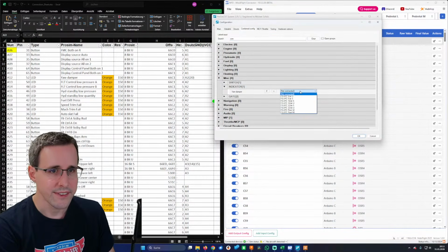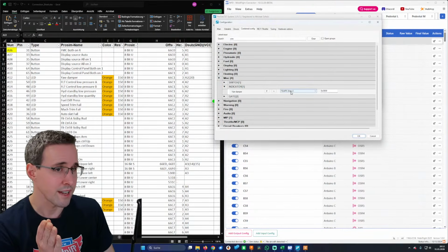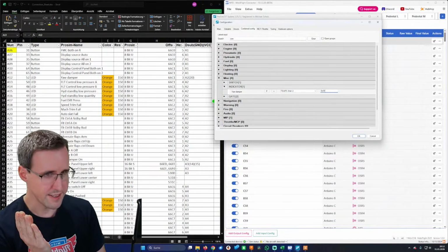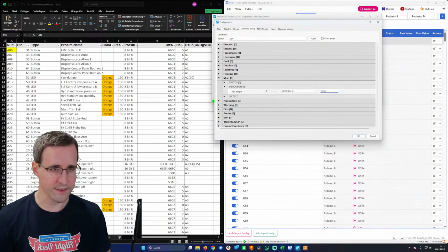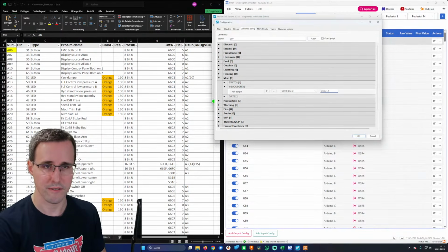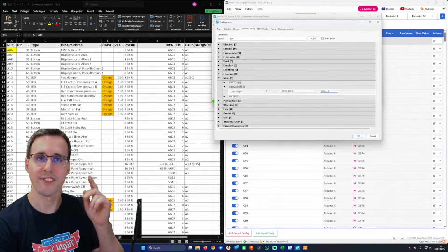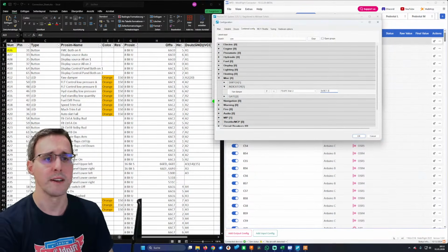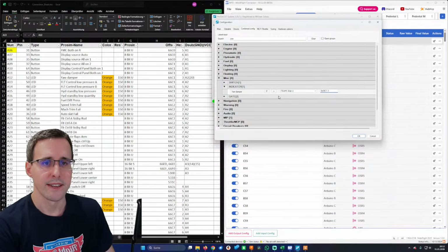And here you can insert that I want to use an FSUIPC offset. This is what I have done until now, and then insert here 66C1.3, because it is the bit number 3, not the 3rd bit. It starts from 0, the counting, but I think you get the idea. Yeah, and this we don't need anymore.